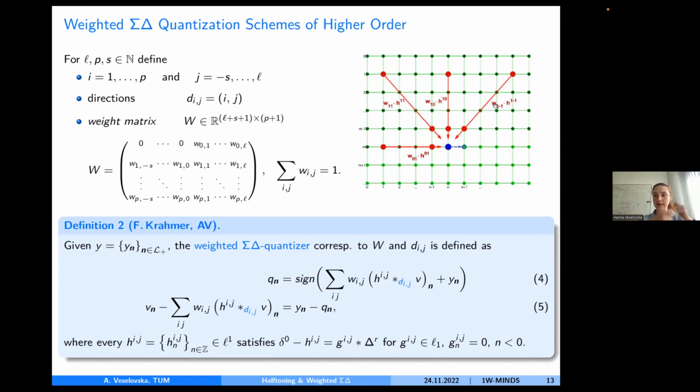You convolve in different directions for your state variable. You collect the error you have computed before by computing these convolutions, and then to compute the 1-bit sample from your initial sample, you sum up all the directional convolutions that were computed with these feedback filters and the state variable, okay?